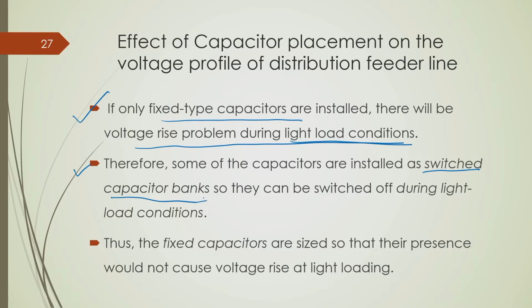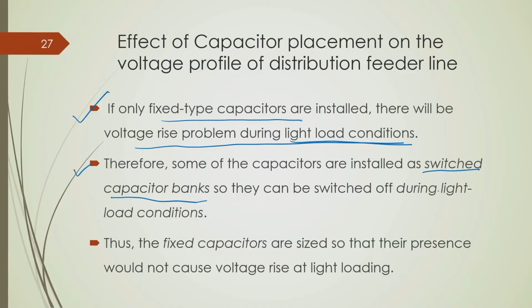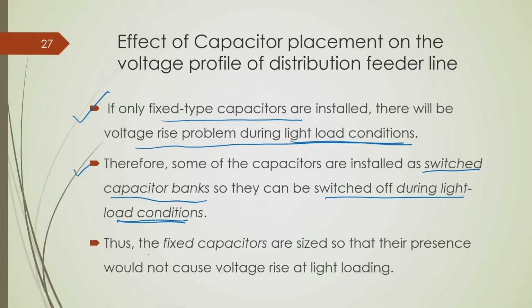It means that they will be used only if these are really required, or only whenever there is a peak load condition. So, they will be switched off during light load condition, so that at light load condition this degree of capacitive compensation becomes low. Okay. And there would be of course some fixed capacitors which will be present throughout the day.